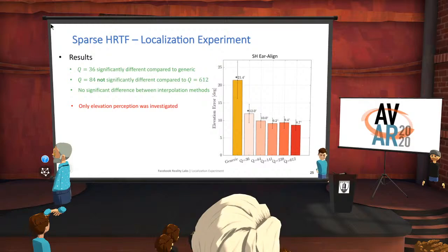All right, thanks. Just a short question. The barycentric, it was interpolation on the magnitude only, right? It's not the complex. Right, the barycentric is using minimum phase representation of the HRTF. So we're doing also barycentric on the delays, on the ITD. You interpolate separately the delays and the magnitude, and then compose it as a minimum phase function. All right, thank you.